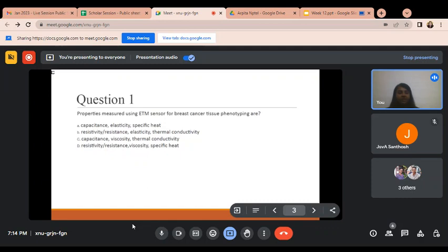And after that, what is the step? At first, if you want to fabricate a piezoelectric pressure sensor or piezoresistive pressure sensor, what will we do? The main process is at first to deposit the material. Then what process will follow? The patterning, which is a part of photolithography. Then after that we etch. The main three processes are first deposition, then patterning, and then etching. So do you have any idea about the deposition process?